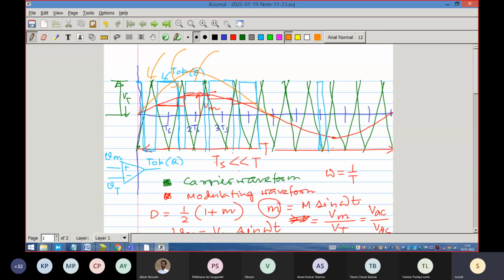Distortion in what sense? By looking, you cannot see much distortion. You will see that the waveform is not switching enough number of times. It is expected that every switching period there will be switching, but when it saturates, in that period there is no switching. In one sense you can feel that it is distortion. In another sense you can feel that it is a less complicated waveform. But this less complicated switching waveform is a problem, because it produces low frequency harmonics.